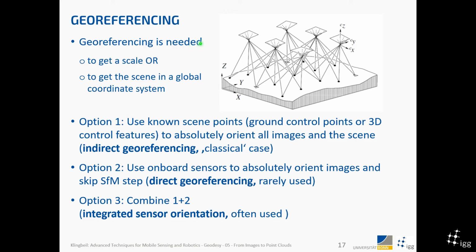So how do we do that with this image-based system? I explained that quickly already. If this here represents the bundle of images which have been taken, and we have on the ground all these object points which are seen in different images, then the whole structure from motion pipeline estimates the position and orientation of the cameras and the position of these object points.